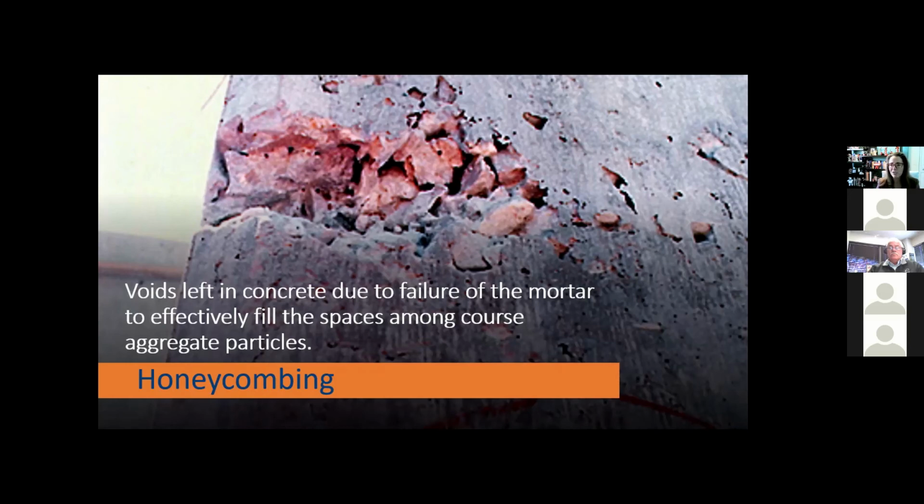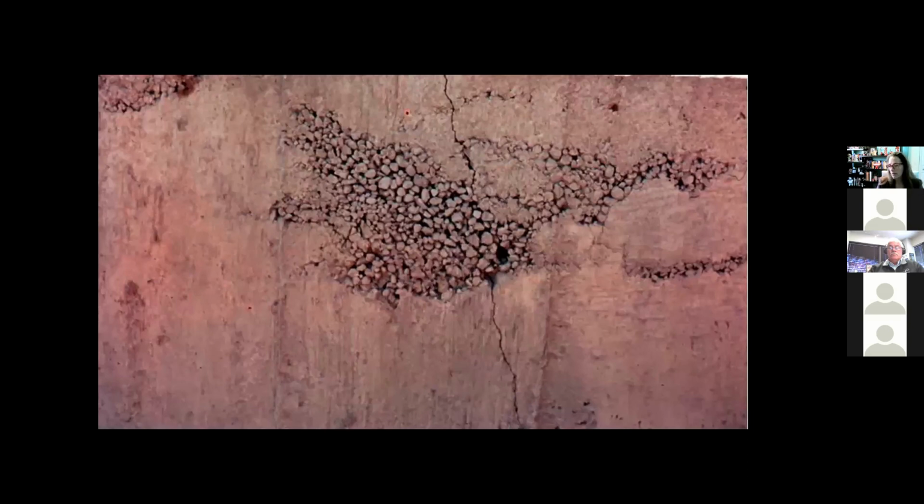This could have been a spec that restricted slump and flowability and then caused this to happen. Maybe it was the method of construction. Maybe there's another way, pumping or using proper ports that could have gotten this to be a more cohesive structure. We also can get places that the formwork leaks, and you can get sand streaking, and you can get areas where paste leaves the structure. There's bigger issues in this one.